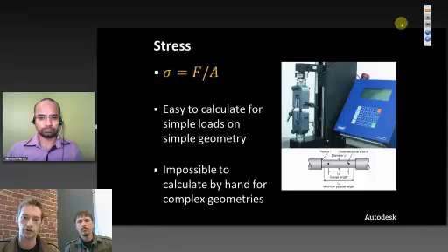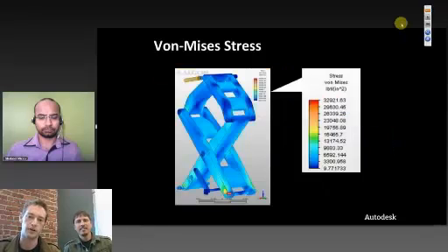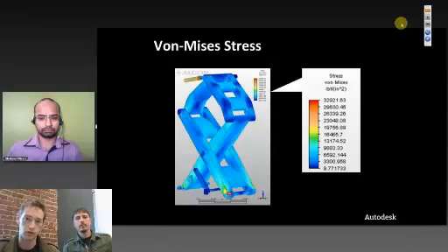And the next thing I want to talk about is strain. Next slide. Oh, sorry, actually, before I get to that, I want to talk about von Mises stress, which is a kind of stress in a way. It essentially combines the shear stress and the axial stress, normal stress that would occur in an object to give you one number, and then for ductile materials such as steel, aluminum, titanium, most metals, and most materials you'll work with, the von Mises stress is empirically the most accurate measure of failure. So it actually says, outside of these bounds, this material will fail.